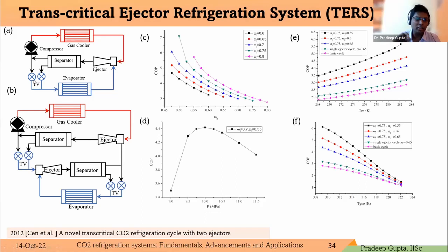Actually, if I can write something, there is a relation: the entrainment ratio is equal to 1 divided by 1 minus H. It's not always true because we cannot control the ejector entrainment ratio very accurately. To just balance that equation, ER equal to 1 divided by 1 minus H, we provided this throttle valve. So the mass flow rate here may or may not come. If the equation is satisfied, the throttle valve which has the vapor may not even open. Otherwise, it opens only for 5% or even lesser, just to control the mass balance in the ejector.